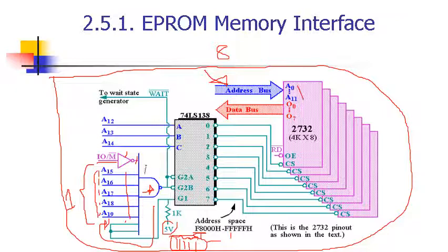This gate is an 8 input NAND gate. 5 inputs are made ones from your address most significant 5 bits, and a sixth input of your NAND gate is made 1 through this signal, and we have additional 2 ones coming from this source.